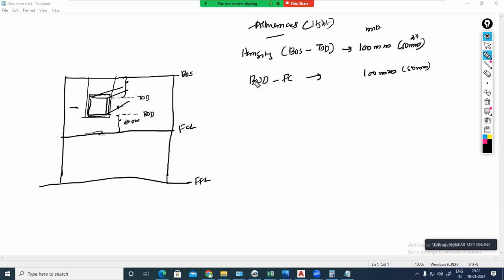How much? With respect to the type of insulation material, it may vary. Nitrile rubber might be less than 25 mm. But normally, if you are using glass wool, 25 mm thickness has to be provided inside a duct, and outside a duct, 50 mm. But that is also with respect to the conductivity of the thermal insulation material and the thickness as well. Conductivity we can find from the insulation chapter of ASHRAE. If you know the conductivity value, you can find the thickness. Resistive R value is also there.